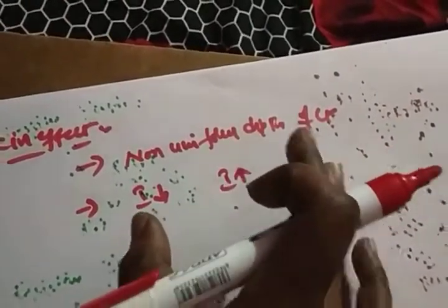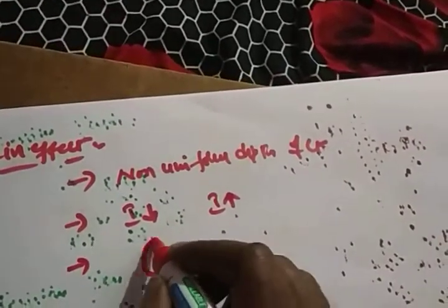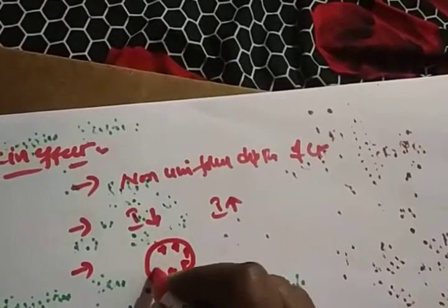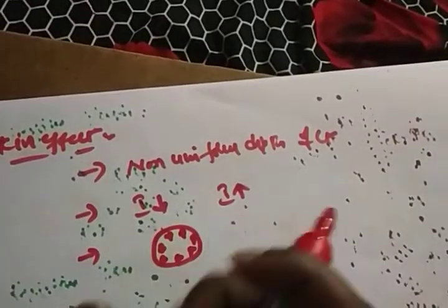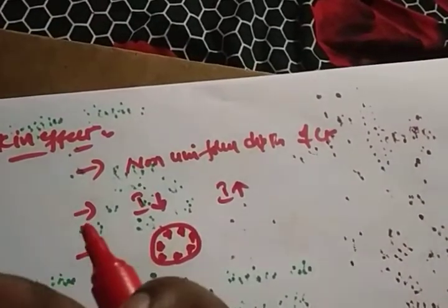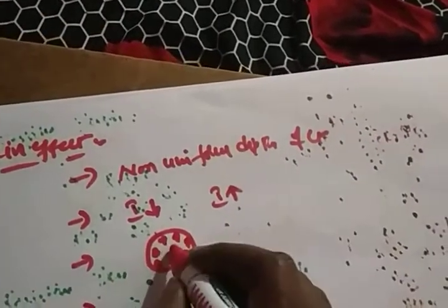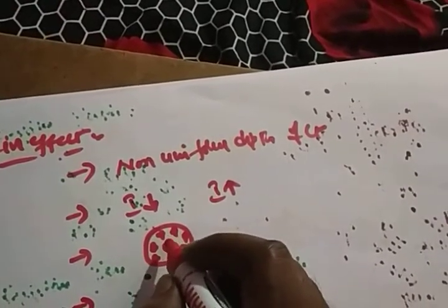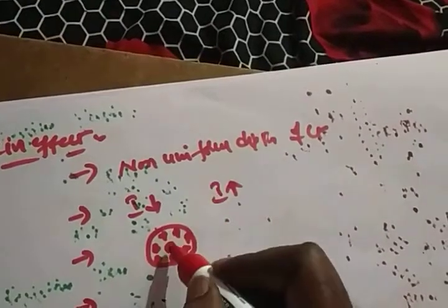In a single conductor, while you are pushing the power, different currents are available in the conductor. So this is definitely a problem, and this effect we call the skin effect. If you take a conductor, the current always flows on the outer surface. In the inner part we don't have any current, so there is a waste part in the conductor, and the cost for that is also wasted. So we need to avoid this. This inner part, which has some copper wire turns, is a waste part, and the cost is based on it too.